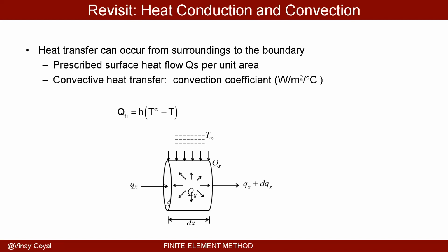You also have this idea of heat conduction and convection. I discussed this already, but in essence, you can have a very hot component, and you'll be seeing that in the very next project. A very exciting coupled thermal problem where the electricity being conducted through the wire is transferred as heat to the heat sink, and the heat sink is losing heat through convection because you have a fan blowing.